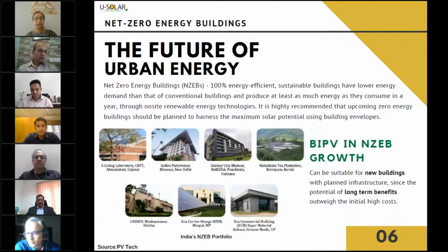So with this, I'd just like to conclude. BIPV is economically viable in certain cases, not everywhere, and especially when the cost of electricity is high. And I think for a net zero situation, this is absolute. If you're looking for a net zero building, putting solar panels on certain facades is part of that journey. Thank you all.